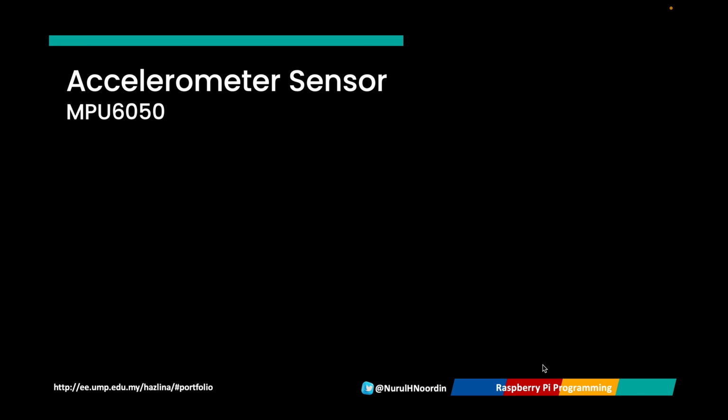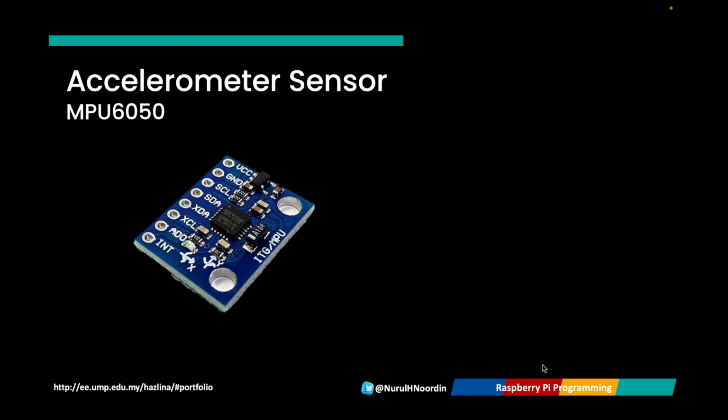Accelerometers are sensors that measure motion, tilt, and vibration. They detect acceleration along three axes, X, Y, and Z. The X-axis represents side-to-side movement, the Y-axis represents forward and backward motion, and the Z-axis represents the vertical displacement. They are commonly used in robotics, gaming control, and fitness wearables. Many accelerometers, such as this MPU6050 or ADXL345, communicate using I2C, making them easy to interface with Raspberry Pi Pico.